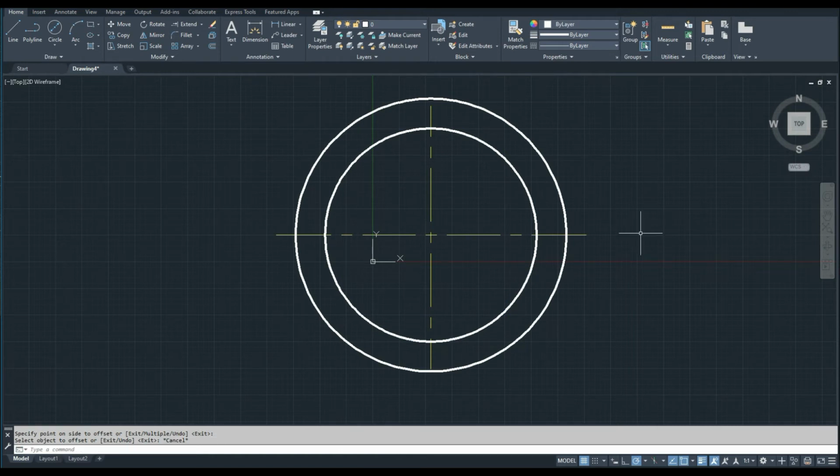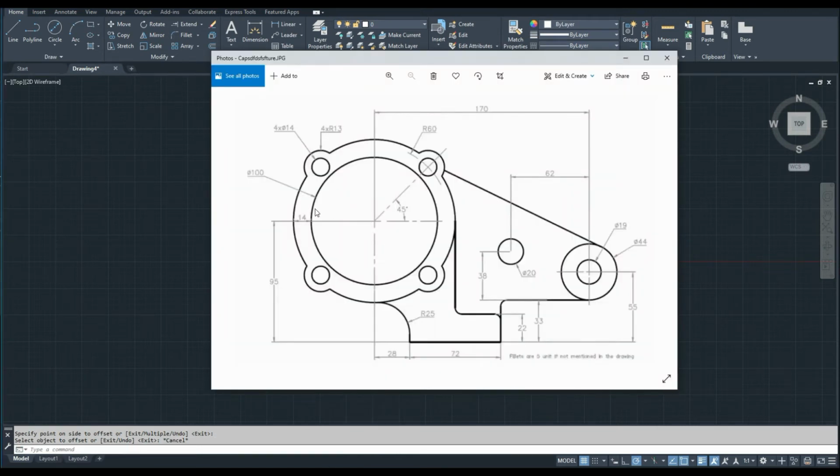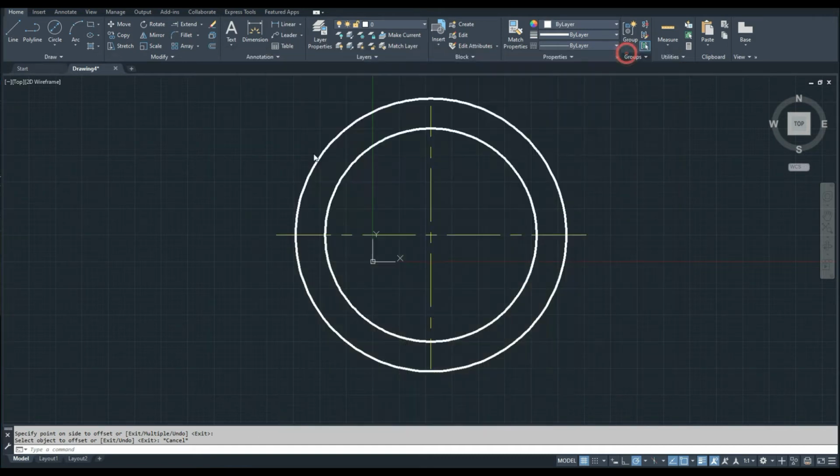Now the circle is ready. Next step, I have this circle and I have this circle. Let me draw the center circle, this one, the center circle, and this line, which is at a 45 angle from the center of the smaller circle. Now this circle's radius is 60. I will go back to the center layer, press escape and be sure that the center layer is still activated.